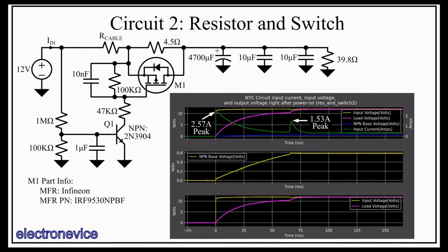But also, the circuit does not do well when the non-capacitive load current is high during the turn-on phase. This is because any load current causes a voltage drop across the current-limiting resistor, 4.5 ohms in our case, which is abruptly shorted across when we close M1. As a result, the height of that surge current that occurs during the M1 shortout is determined in part by how large that voltage drop is. If that voltage drop is large, then we might produce a very large current, and our circuit doesn't work nearly as well at limiting the inrush.